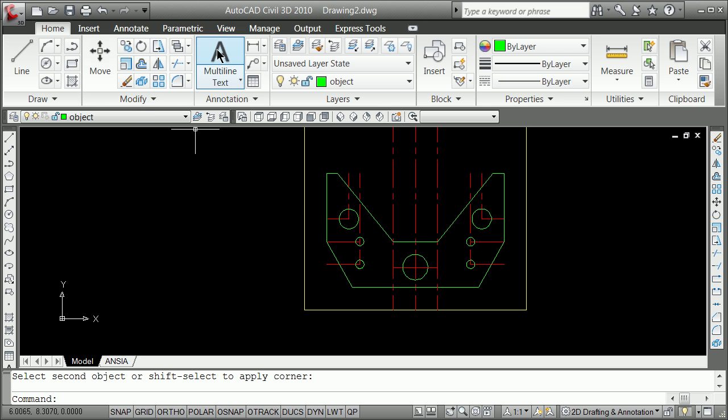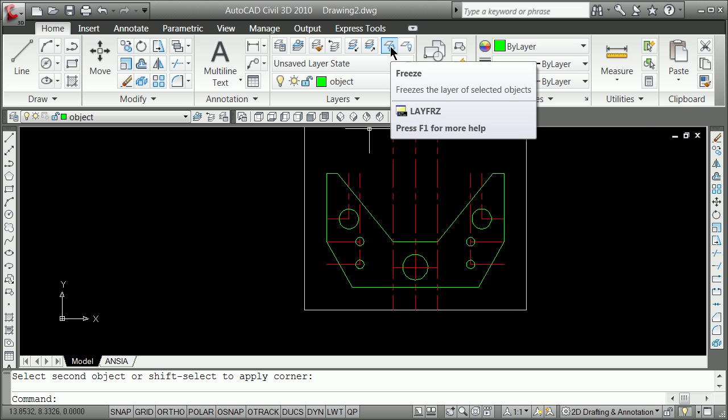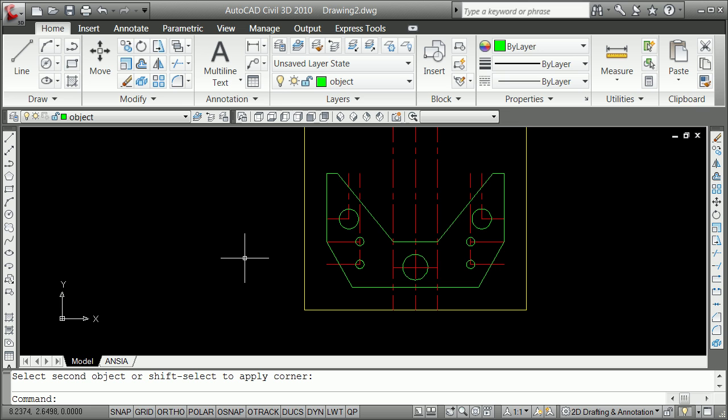And since we have this great ribbon up here, we're going to point you out now to some really nice command, and that is the fact that you're going to want to polyline edit these things together once you've done them. And we're going to see why. Once you've done good line work and everything else, you're going to want to polyline things together. You do that by polyline edit. And polyline edit is a lot better if you isolate a layer or you freeze a layer, the layers that you don't need. So I'm going to show you right now.